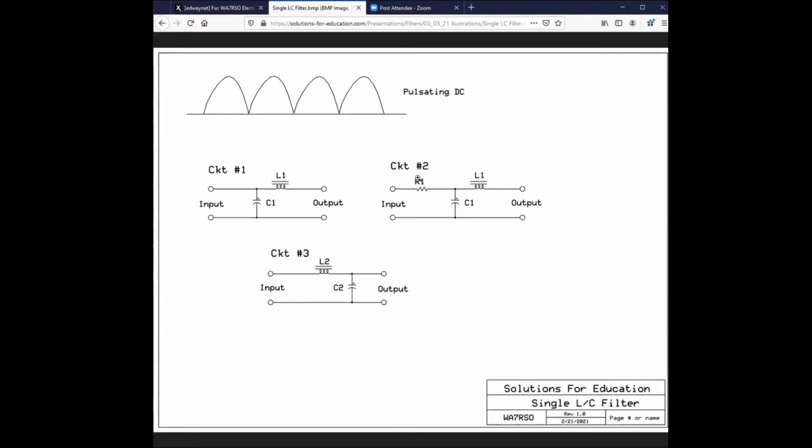Now, going back to this other business, look here. This is obviously the pulsating waveform, as best I could draw it, coming off of the power supply. As the voltage starts to rise, remember one more thing: this is not just a diagram of voltage, this is also a diagram of current. And then you start really bending somebody's mind when you say, wait a minute, if this is a dead short, what's the voltage across the dead short? Zero. But wait a minute, there's a lot of current. Now you begin to teach the fact that current can be an independent identity to the voltage, because it has to do with the ohms that are involved here, right?